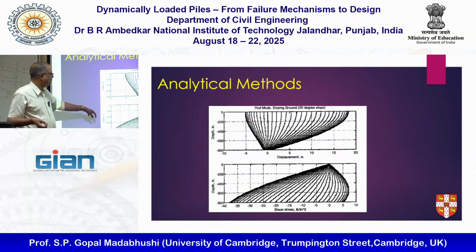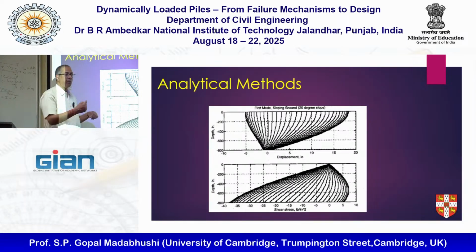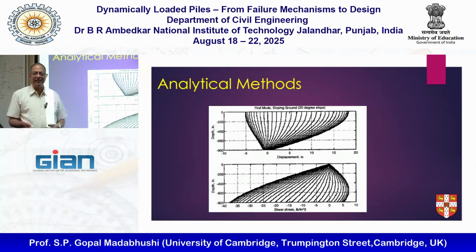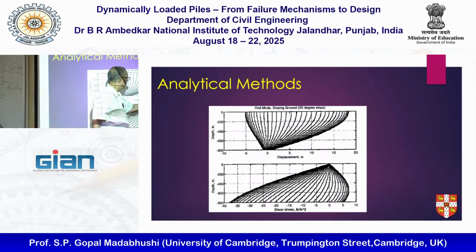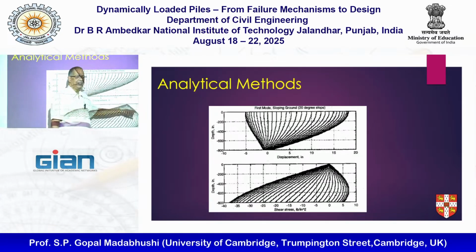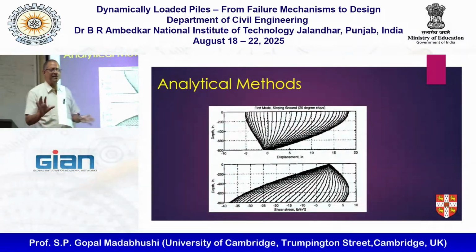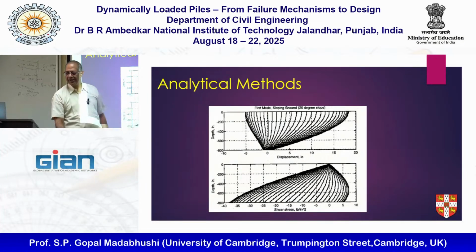And again, you can see how the shear stress is more when it's trying to go upslope and it drops off. As the soil liquefies, obviously the shear stress will become quite small, and that's why it's flowing. So this is quite right that at the end of the shaking, I got very little shear stress in the layers. Does that make sense? Yeah? Okay, anyhow, these are the plots one can get.